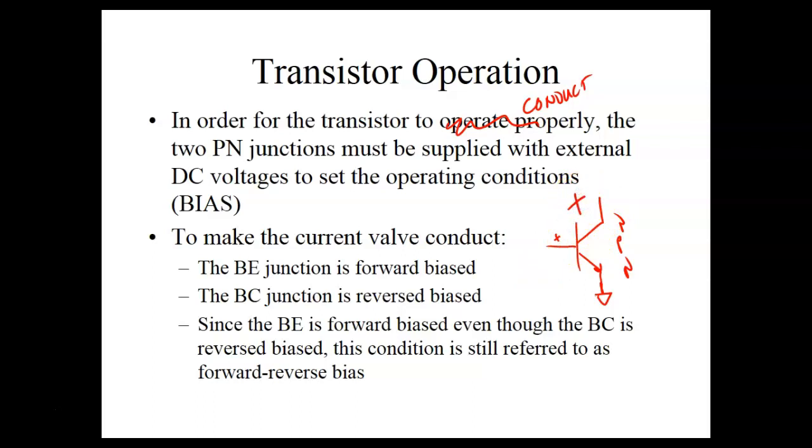And this is the way I teach. I don't teach that the cathode has to be negative and the anode has to be positive. I teach in respect to. So this would reverse bias it, because if you look at that like a diode, you can see that the cathode is more positive than the anode, so this guy is reverse biased.